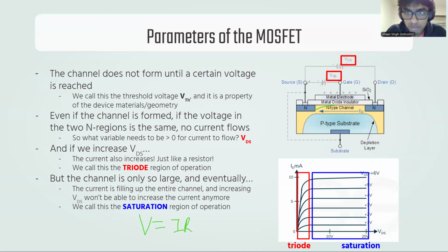What does the drain do? The drain and source are basically symmetric. But since we've tied the source to the main body of this transistor, the drain is where the electrons go. Electrons come from the source and end up in the drain. That's why we call it that. But just remember, because we model current as the flow of positive charges, the current is in the opposite direction.